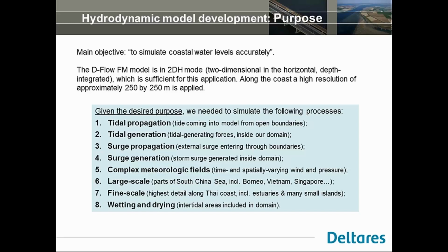For this purpose, we wanted to simulate these 8 mechanisms that I mentioned in the slide. We want to capture tidal propagation from outside the domain. We want to simulate tidal generation by explicitly determining tidal generating forces. We want to simulate surge propagation from outside the domain, but also surge generation by wind inside our model domain.